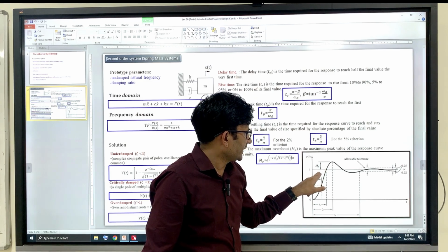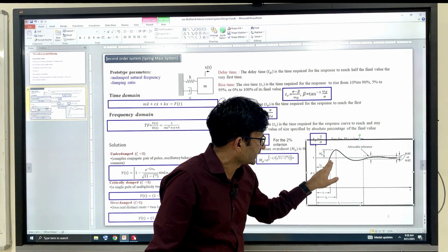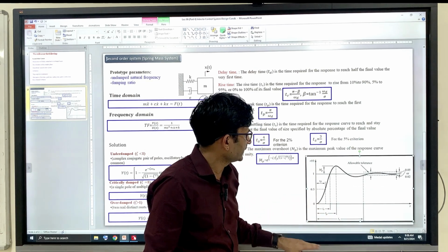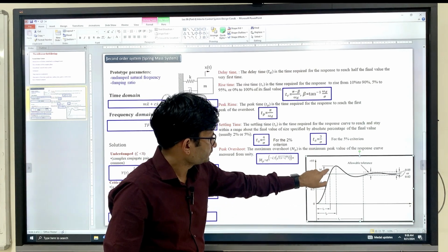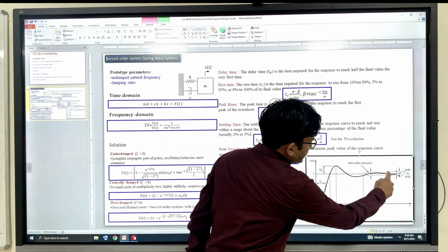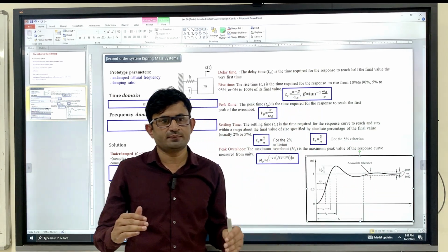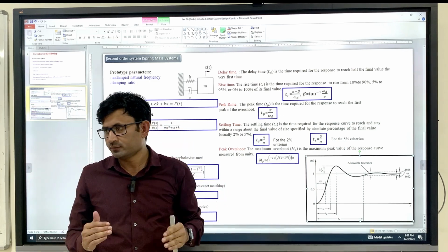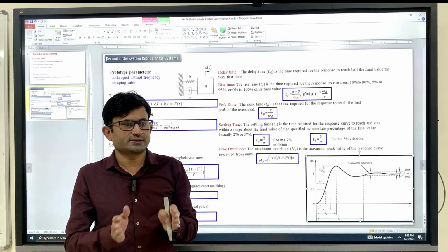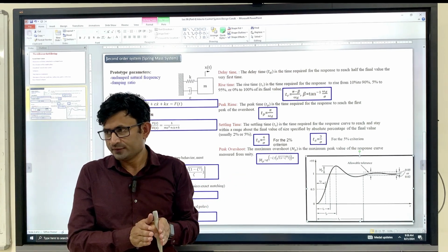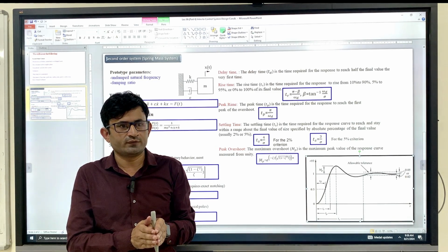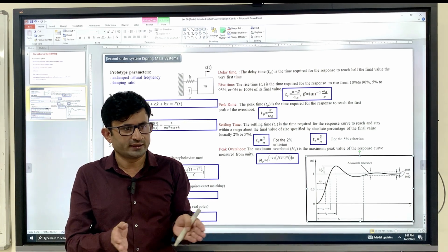By introducing Kd, you can actually smoothen the curve, and you have some steady state error. Steady state error means you are actually not at that point. You have eliminated the oscillation, but you are not exactly at the point B. For example, you have commanded 5 meter, but instead you have reached 4.98 or 4.97.